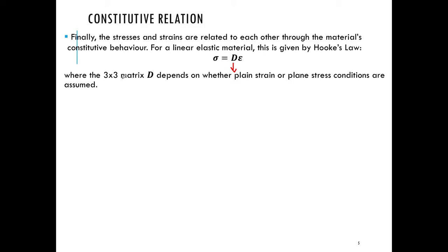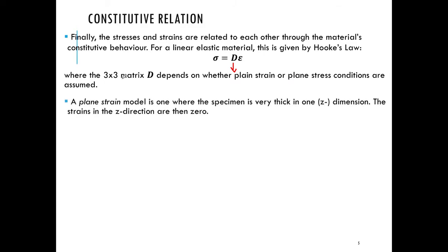Just to recap, in case some of you do not remember from your undergraduate what plane strain and plane stress are: plane strain is the case when we have a specimen which is very thick. If it's very thick, then we can assume that the strains in that particular thick dimension are all zero.